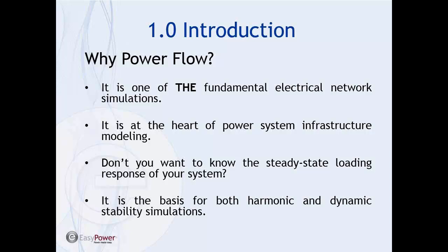You want to know whether, if you add that load or make that transfer or do any type of a steady state load addition, your system will respond adequately. It'll have a high enough voltage, and you're not going to be overloading equipment, etc. So definitely, Powerflow is the fundamental electrical network simulation that's used in the industry.